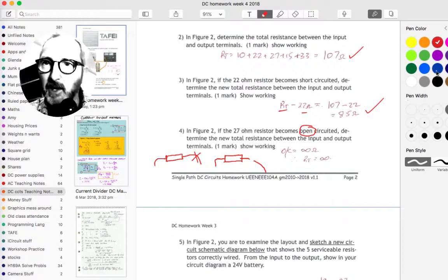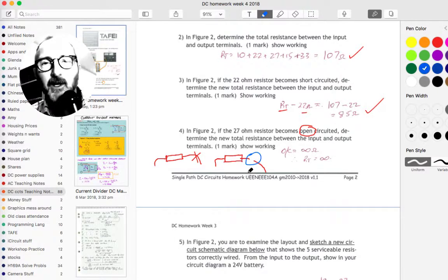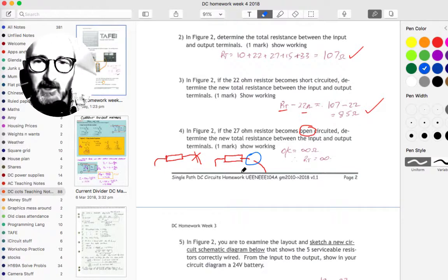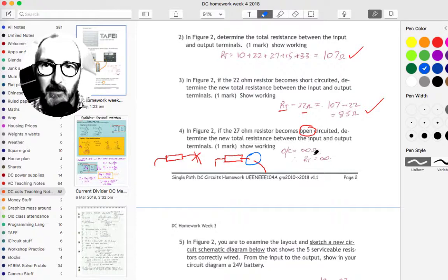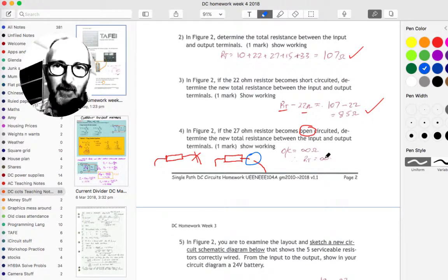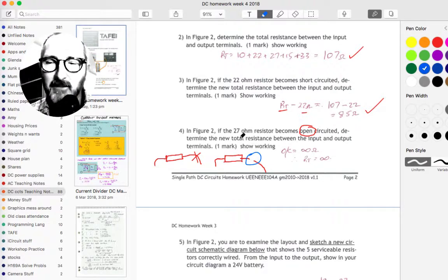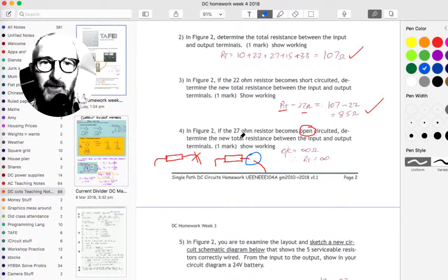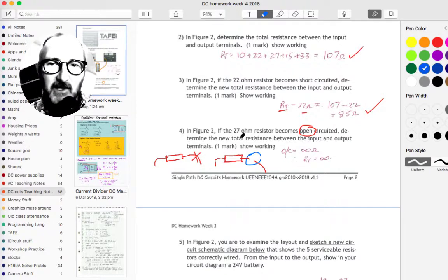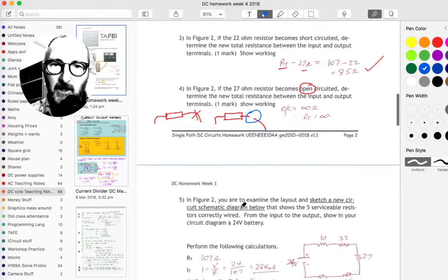So you've got this break in the circuit, and while you've got this break in the circuit, no current can flow. If no current can flow in the circuit, we're going to have an infinite amount of resistance measured across the whole thing. You've got your digital multimeter, you put it on the ohms range, and you go to measure air. What do you get? Well, the meter doesn't change. It just shows OL, or out of range, or infinite resistance. That's all it's going to show.